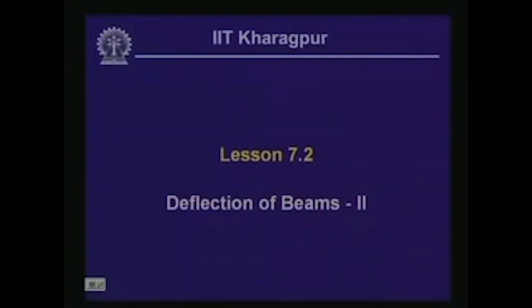Welcome to the second lesson of the 7th module, which is on deflection of beams part 2. In the last lesson we have introduced the concept of deflection of beams, and also it has been introduced how deflection of beams plays an important role in engineering structures. We have derived the differential equation for the elastic curve, and subsequently we have derived the equation for the elastic curve, and we have seen how to compute the deflection of a beam at any point for a